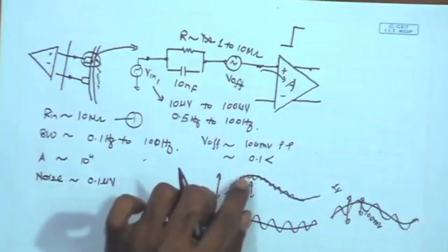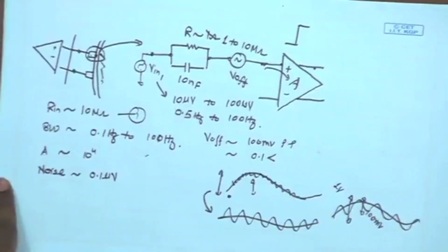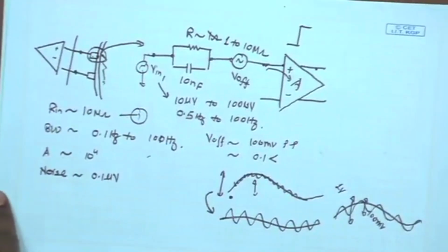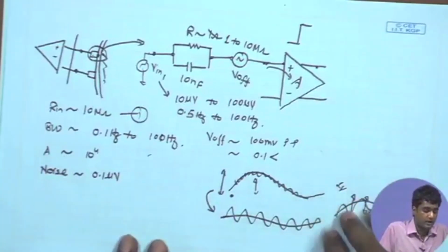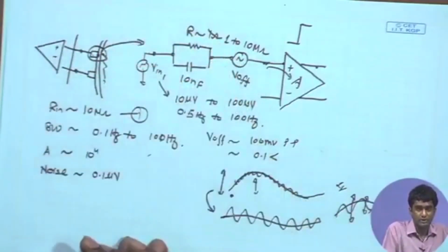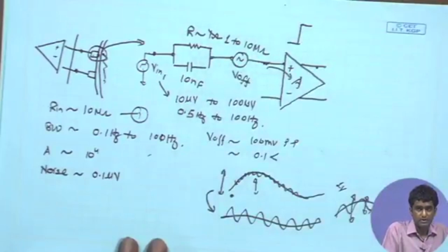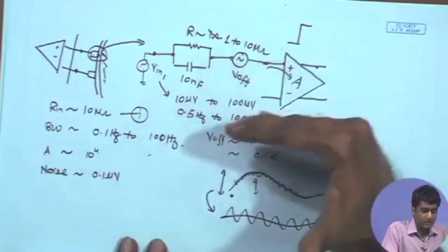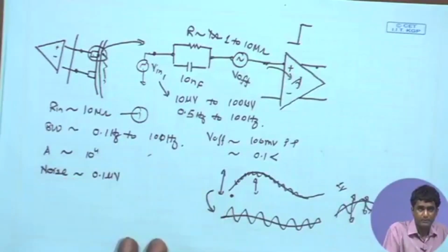Now, we also need to look at some other important characteristics, like say the power budget, what should be the overall power dissipation of the front end system, and that again is dictated by an application. So, if you are envisioning an application where you have a multi-channel interface, you have several tens of these electrodes coming onto your integrated device, you would like to minimize the power dissipation in each of these channels, and the power dissipation again has conflicts with many other parameters, most importantly noise.